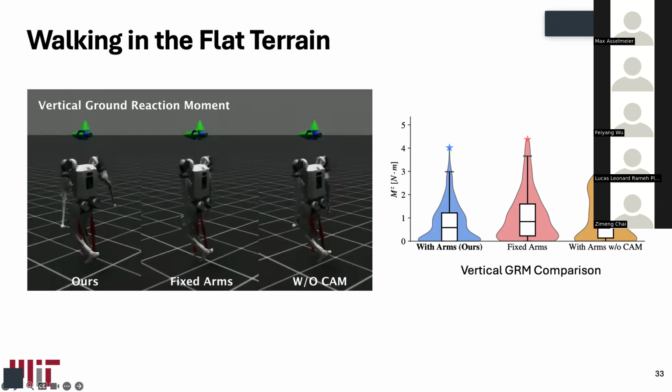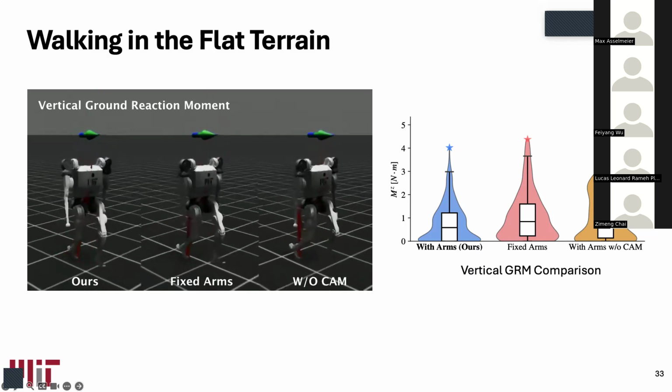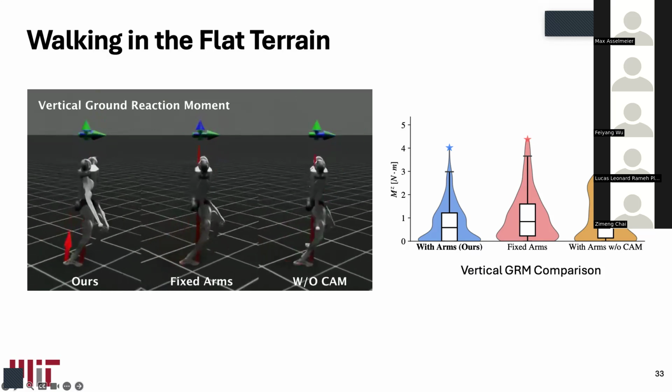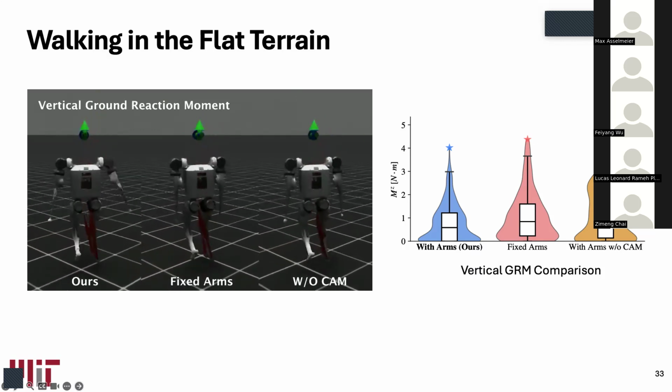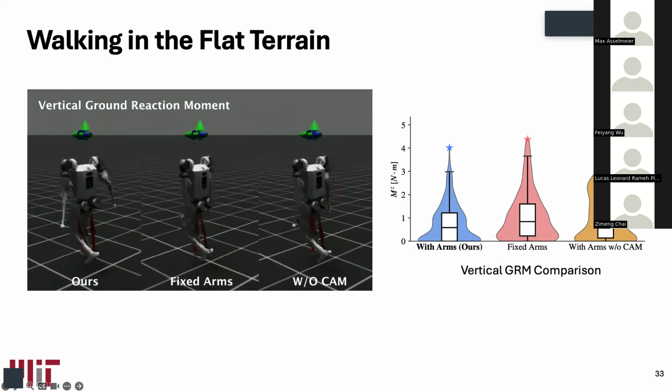Something we've consistently observed when we allow the arms to be completely free without any kind of joint regularization is it often learns to keep the arms up in the air like this, kind of tucked and bent. Our theory is that self-collision termination penalties is why it likes to keep its arms up here, so that the arm is far away from the body and won't touch anything. Yeah. But without any kind of regularization, it always does some goofy thing up here. Yes. So we remove that to avoid that weird motion. We still leave the regularization part.